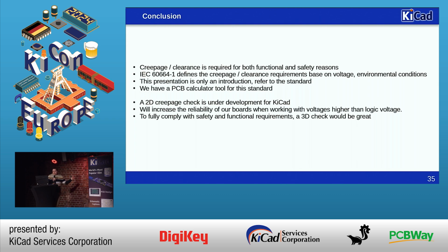As I said, this presentation is only an introduction. It's not enough to know the standard by itself, because the standard is 80 pages long. But we do have a PCB calculator tool for that, which allows us to know what creepage and clearance requirements are. And at the moment, we are trying to make a creepage check in 2D work in KiCad with some limitations, but that would be a first step.